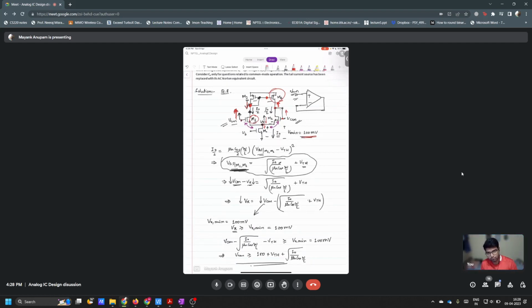So we can show it in LTspice, sir. Means how we can verify it, sir, which transistor will go into the triode region while calculating the maximum and minimum voltage. That scale range is there, no, sir. Yes, you can also check with LTspice, but for that you need the model files and all.